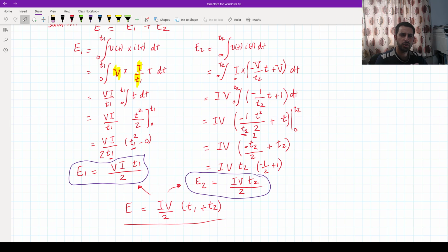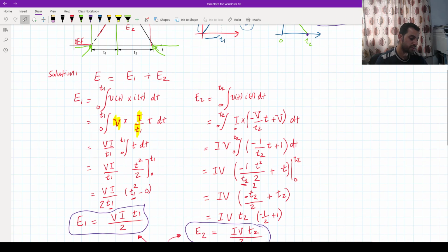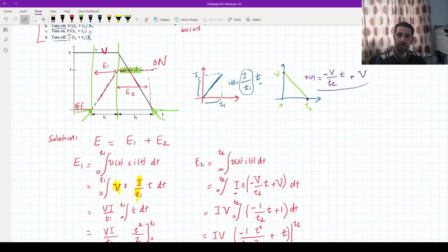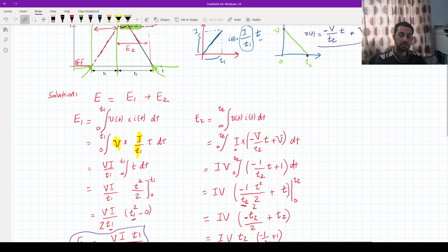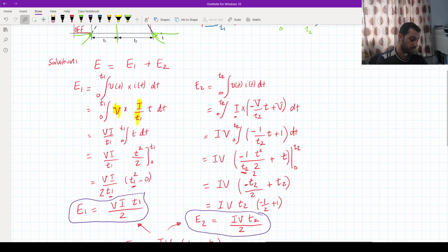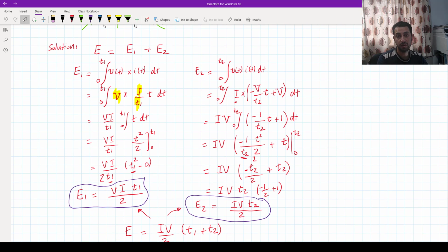And if that's very high, you are going to use that figure to calculate the average power and also to decide whether you need a heat sink, or if that is very low and you don't need a heat sink for this. So all these things we are calculating now by hand, all the equations, but later on I think you can use software just to compute everything for you. But if you know how to compute that, it's good, because some of the researchers now produce new models for computing more accurately the switching and conduction losses. So yes, we have to know the basics before we use any other software.